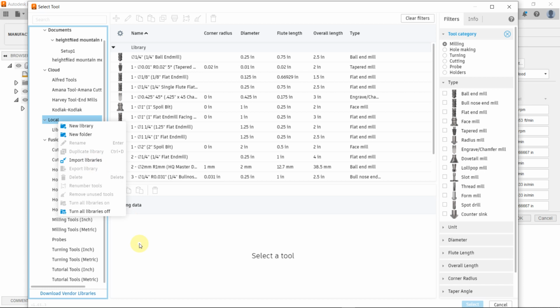We set the length of our tool at the machine. Because when you put it in the holder, there's no way to know exactly where it is in the z-axis. We know exactly how thick it is, but we don't know how long it is.